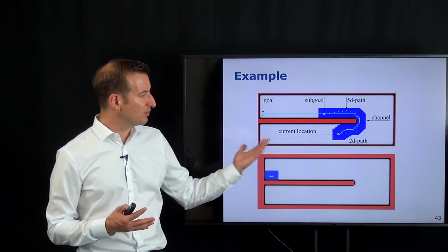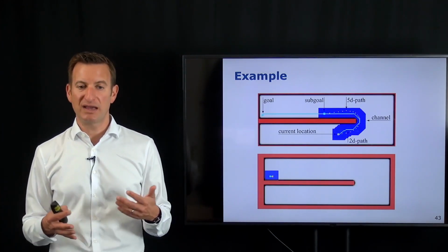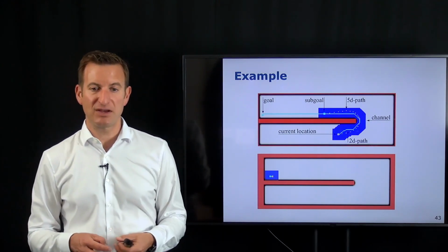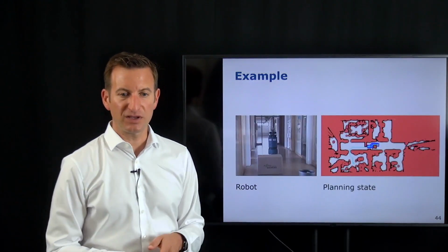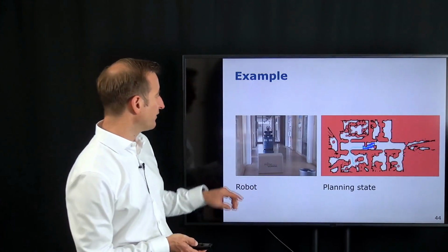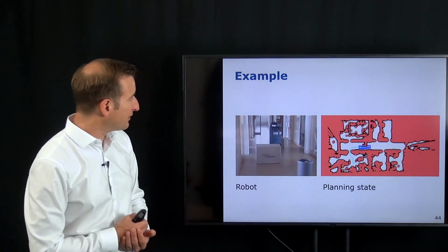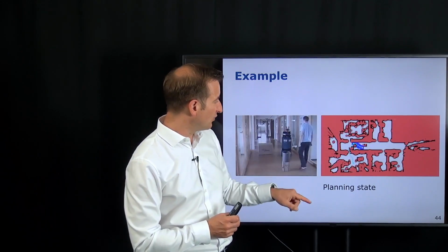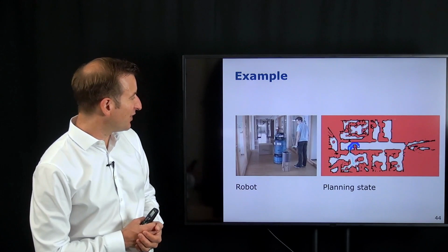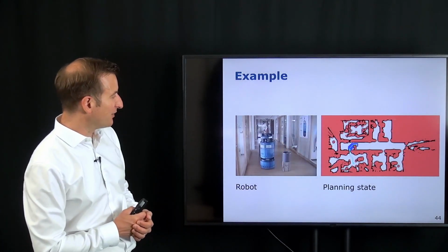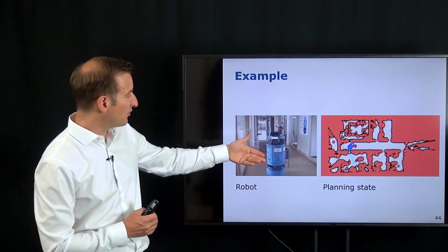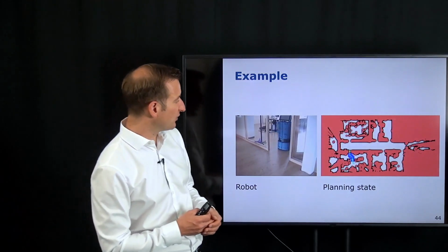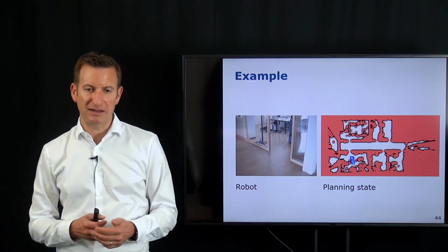And if we can execute this, which is the case here, multiple times per second, we can actually run that on a real robot and update our path based on the information that we see. Also a small example, in the real world, the system navigating through the environment, Robot Albert at the University of Freiburg, and you see here the planner that updates the map. You see this channel, that's me over 20 years ago doing this experiment, how the system navigates through the environment and smoothly drives around obstacles, and is also able to drive through rather narrow passages or a doorway in order to reach the final target location.